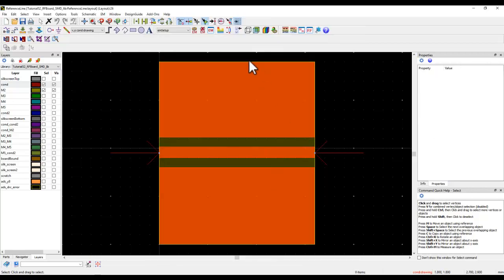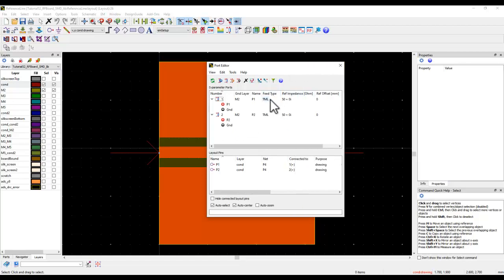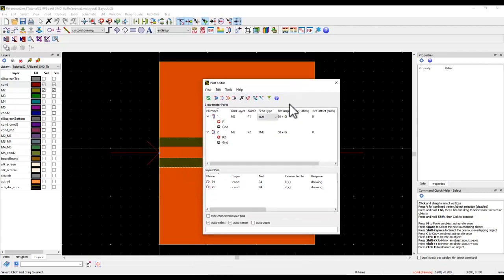Now, in order to set it up for simulation, I have connected two ports on either end of this line. And under port setup, I have declared the calibration type as TML instead of auto, which is by default there. So TML is a fully calibrated port. Essentially, if this line is acting as a perfect 50 ohm line, you can see a 50 ohm getting connected to 50 ohm. So I should get a pretty good return loss and the insertion loss as predicted by my line calculator.